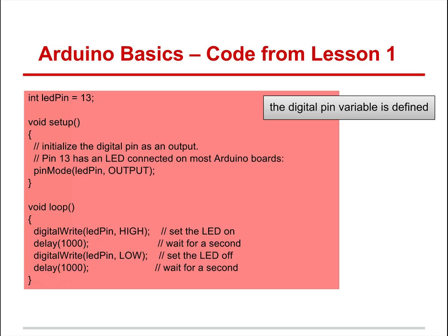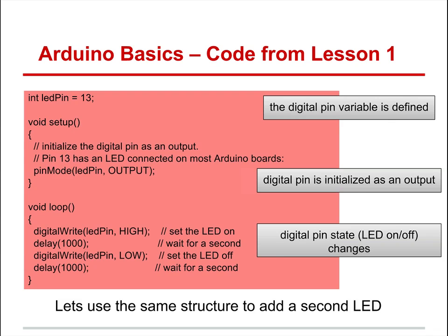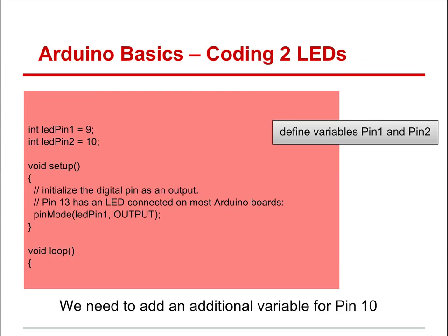So you're programming it. Remember, on the first pin, we defined the pin as a variable that we were going to assign to the pins. We made the outputs, and then the actual action, where we did digitalWrite, delay, digitalWrite, delay. Well, if we want to do two LEDs, one way we could approach this is integer LED pin equals 10, integer LED pin equals 9.